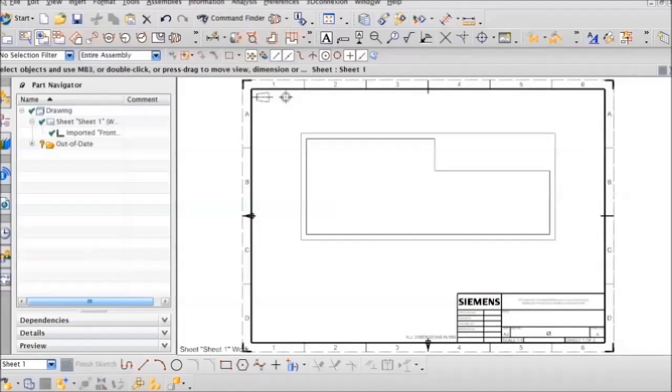And before telling the actual story, I should mention two things. First of all, you should consider the implementation of PMI if you are using these techniques often, because PMI usually works better in these cases. And second thing is, usually from my experience it is around 5% of the dimensions on the assembly drawing which are getting broken, so it's quite a small value. You don't need to define all the dimensions with the use of this technique.